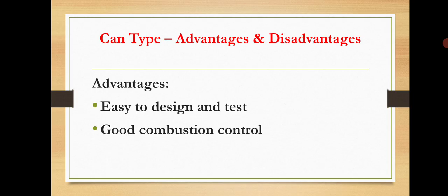Second point, good combustion control. Each can has its own burner and fuel supply. Combustion conditions can be controlled individually, leads to stable and efficient burning, improves overall engine performance due to better combustion.